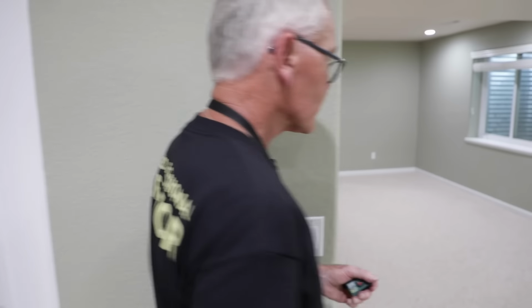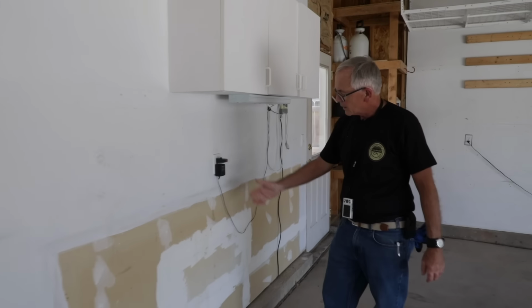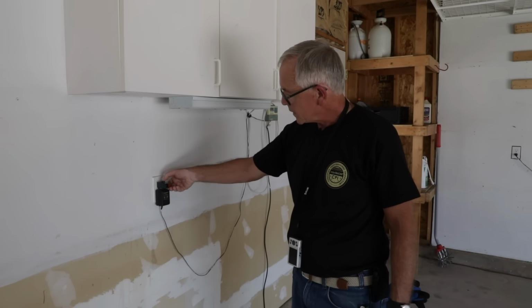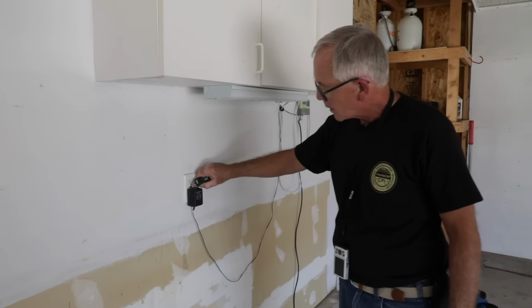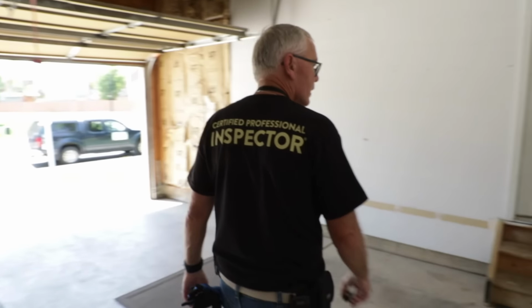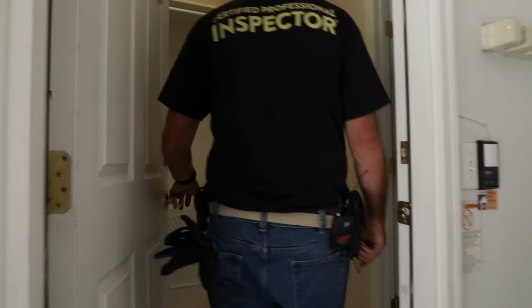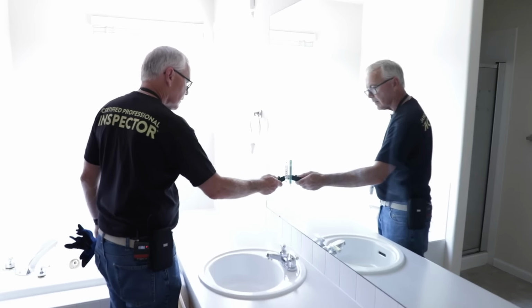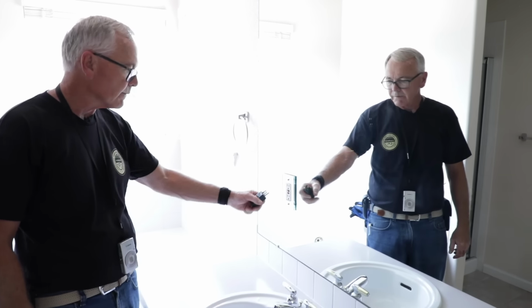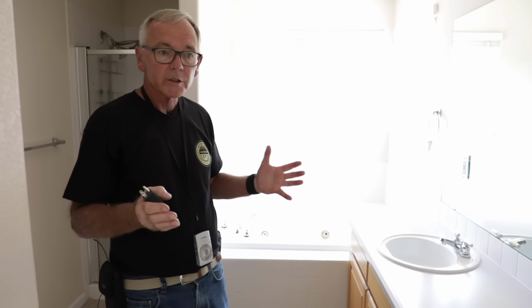So now I think I'm going to look in the garage. So I'm here in the garage, and we've got one GFCI here. This one's still energized. So I'm going to test this. Okay, it's back on, retest. Perfect. So we still need to find the GFCI for the half bath. And my last suspicion is that it's up in the master bath. So we've got to go back up there. Okay, so the master bath GFCI feeds the half bath on the main level too. So all of the bathrooms are circuited together. That will conclude our GFCI testing.